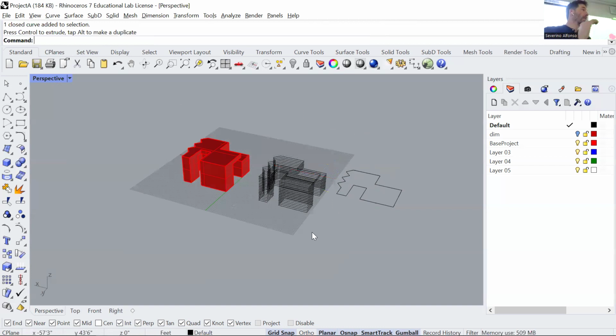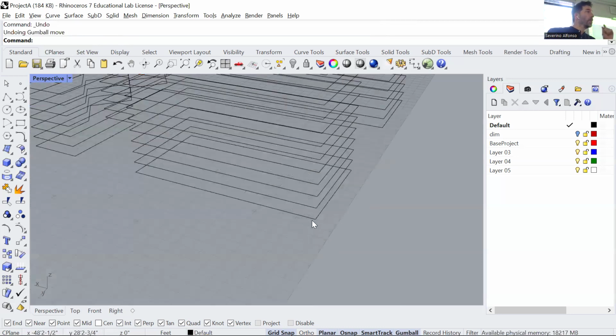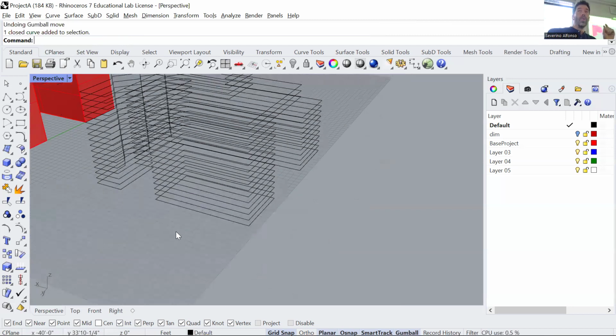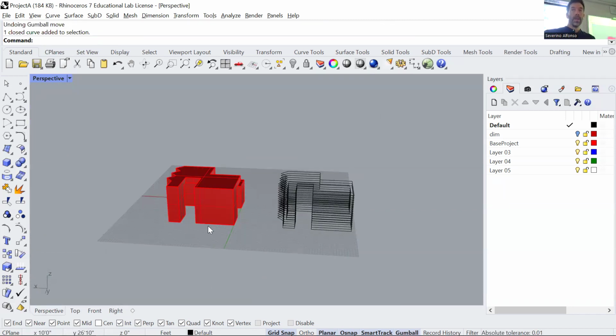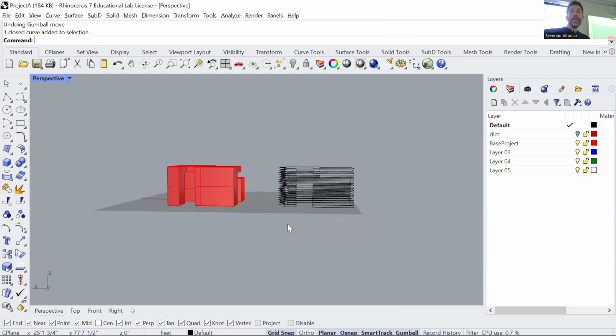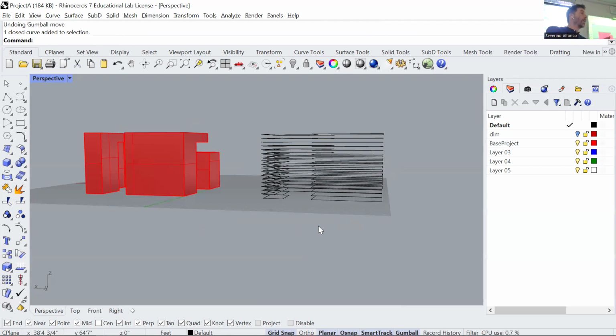It's almost like applying the section command multiple times and having a parameter of what is the distance between each of those cuts. That's the contour. So how can we use it for laser cutting? Well, if we know the thickness of our material, we can say, give me a number of cuts in this direction, distant the thickness of my material, and then you send this to the laser cutting. It cuts it and you glue one on top of another.